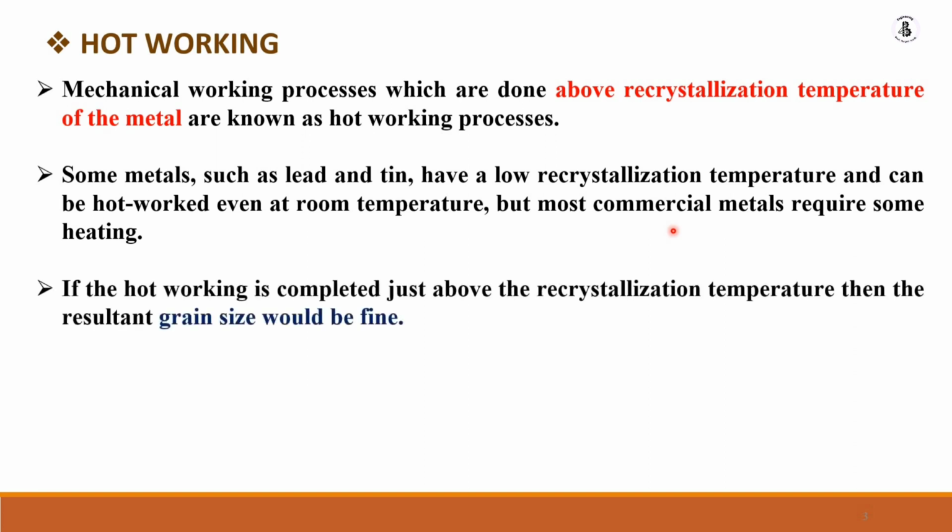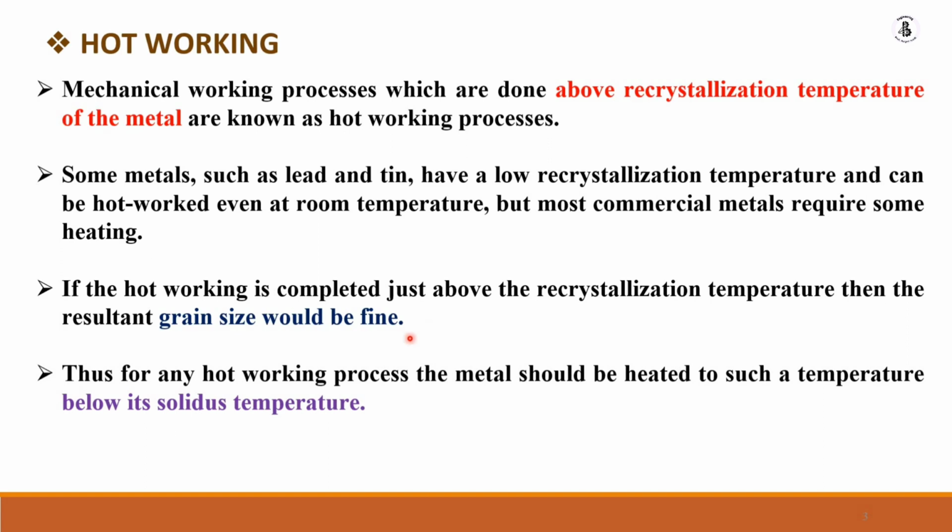After this, if the hot working is completed just above the recrystallization temperature, then the resultant grain size will be finer. Hot working requires less force. In the case of the hot working process, the metal should be heated to a temperature below its solidus temperature line.